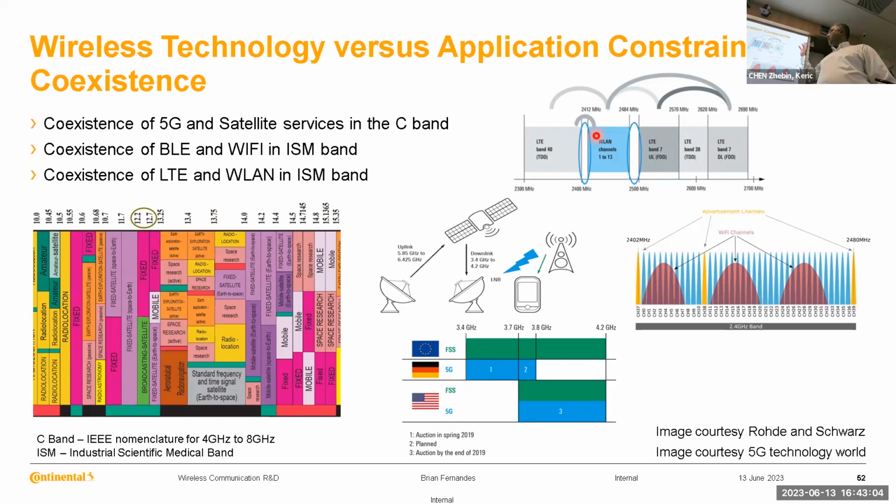Of course, in Wi-Fi 7, there's a lot of sensing being done so that the router could use a different channel and then communicate to the device to shift channels and things like that. So these are some of the mitigation efforts currently being done in some of the newer standards. But in the older standards, we still have this restriction, especially as BLE also operates in the same band here. So there is strong potential interference from LTE band 40 into the BLE spectrum.